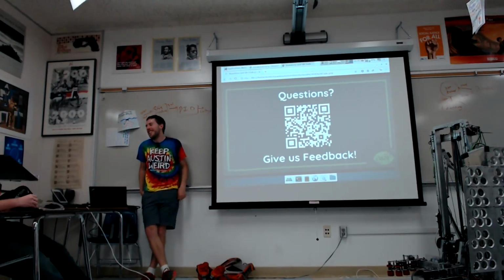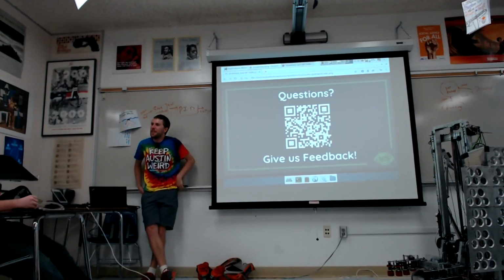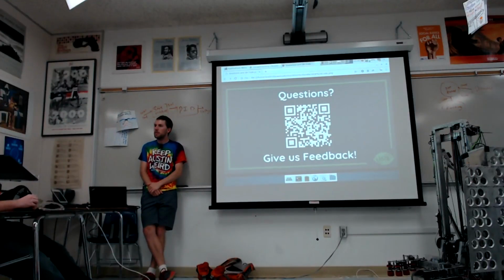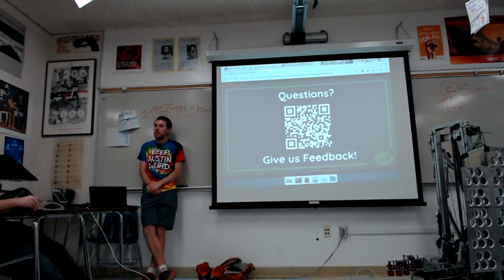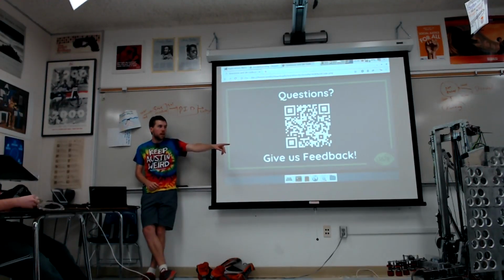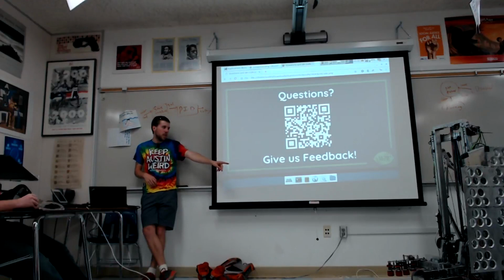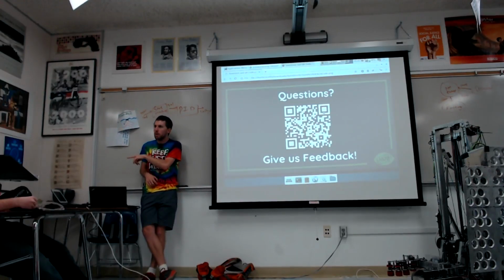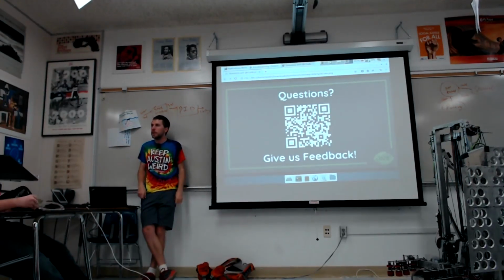I've tested all of this. And the biggest issue I find is how can we know that our model is accurate? Otherwise we just have to build it and trust it. Or you have to bootstrap it. So if we were going to be super rigorous right here, the next step would be to feed motions in here, capture data, and then feed the same inputs into our model and look at how well the two compare. And we tune our model with that all the time.